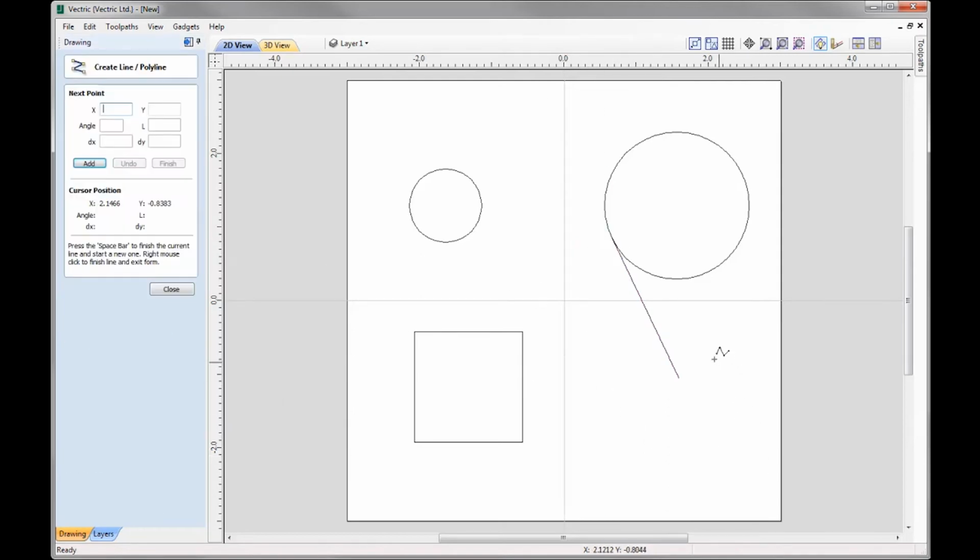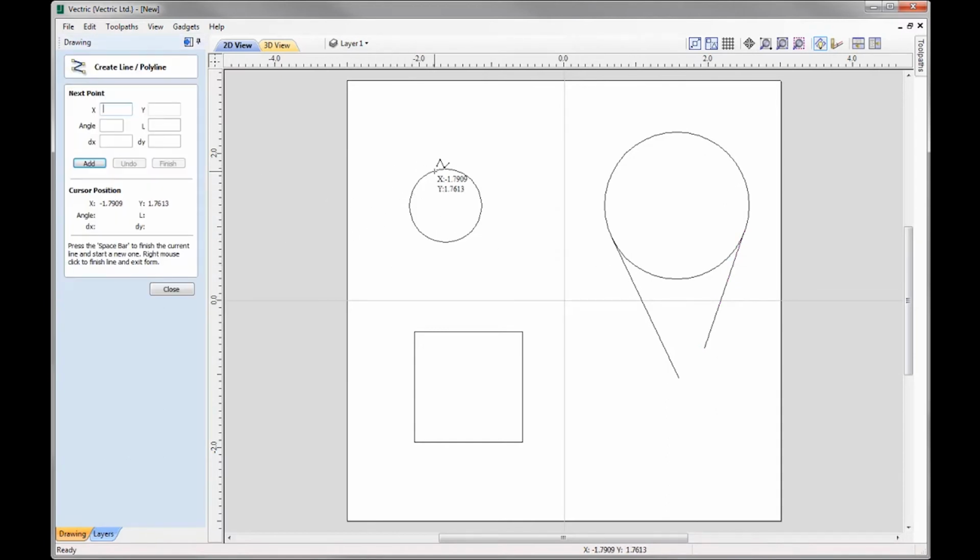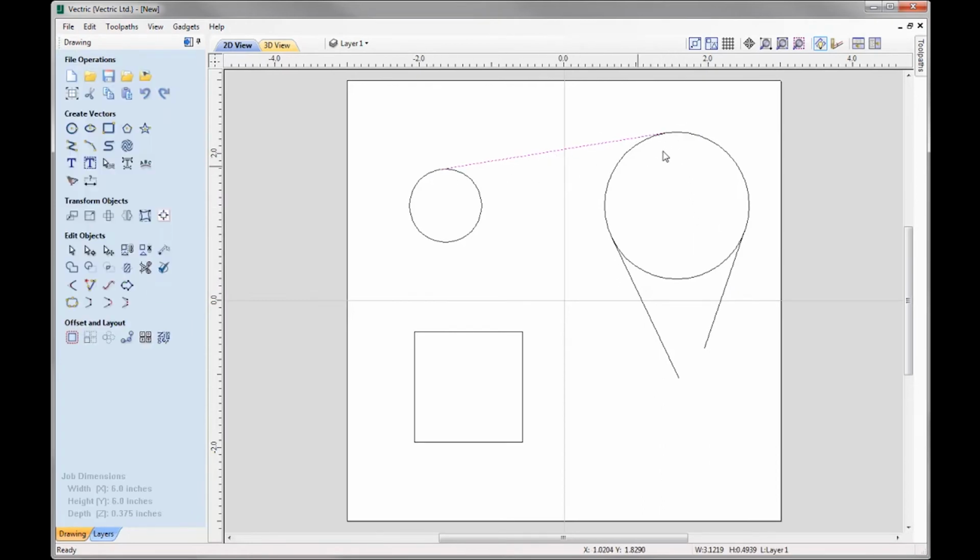So you see that again, let's just hover over the circle, press T, and then that will create that for me. Okay, going between 2 circles, simply click on the one circle, click to another circle, then press T, and then it will create the tangent line between the 2 circles there. So very handy tool for us to be able to accurately create these lines.